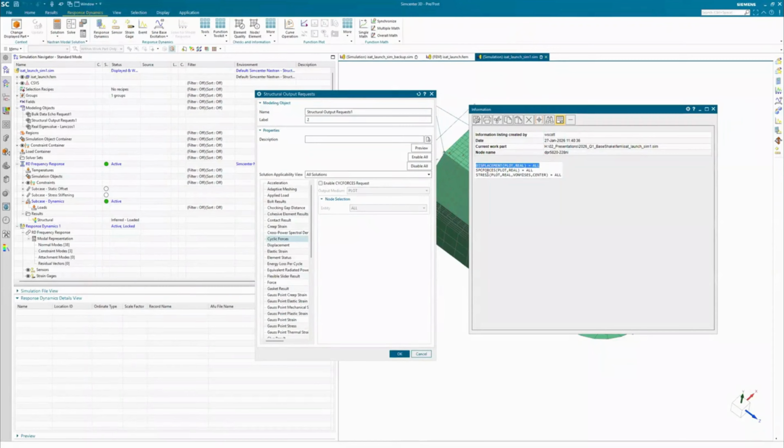Another question here. Is there anything we need to know or pay attention to when using response dynamics with external superelements? Does the normal workflow apply here as well? I ask because Simcenter 3D normally works with the OP2 file as the default external superelement. However, when it comes to OP4, manual input deck intervention is required.